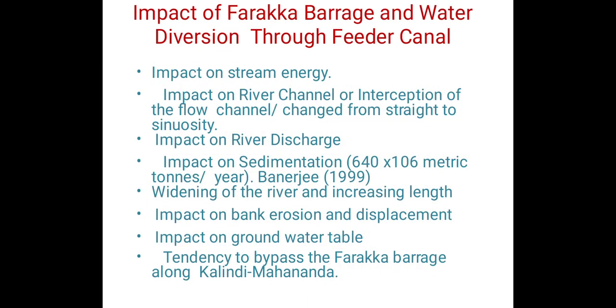Impact of Farakka Barrage and water diversion through feeder canal. Impact on stream energy, impact on river channel or interception of the flow: channel changed from straight to sinuosity. Impact on river discharge, impact on sedimentation, widening of the river and increasing length, impact on bank erosion and displacement, impact on groundwater table, tendency to bypass the Farakka barrage along Kalindi Mahananda.